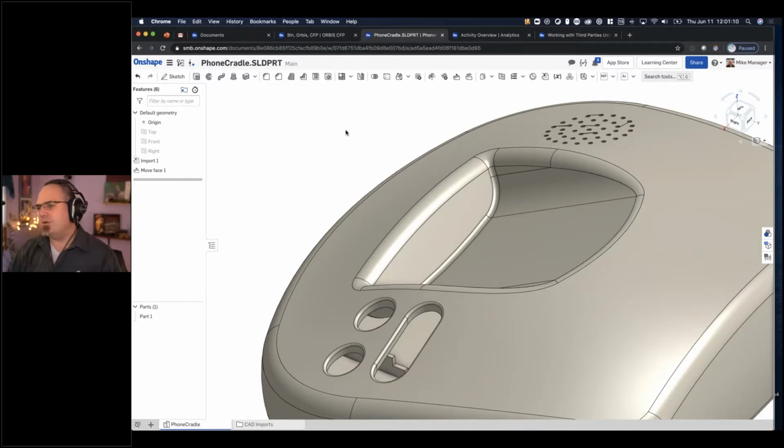Like if you use the same motor over and over again, and you import like 5 assemblies that use that same motor, it's going to import that motor again, but you'll just replace that motor with the one that's in your central library. And that's something we teach on our onboarding typically.